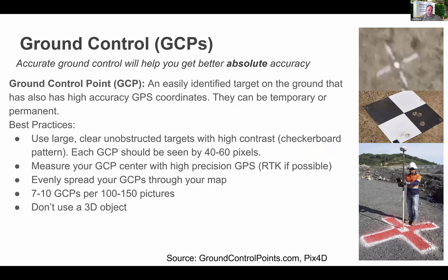There's more, but the main two reasons are that you want to do change detection and you want your image products to be completely aligned from one flight to the next, whether they're the same day or next month or the next year. But you can use ground control points, or GCPs, to lock your processing outputs into very accurately positioned results.